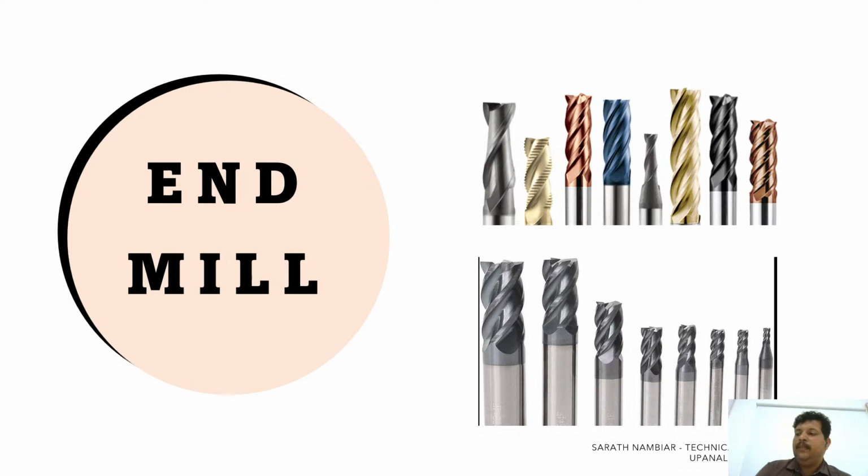Imagine you are cutting a straight groove in a plate. You want clean edges and a flat bottom. There, what will we do? We will use this flat end mill. Why? Because it will give flat corners. Now just imagine we don't want flat or sharp corners.